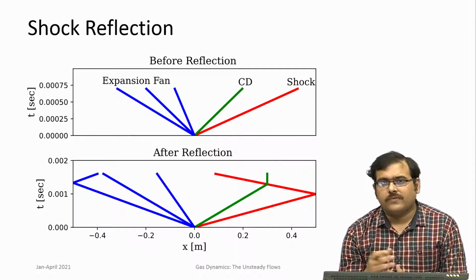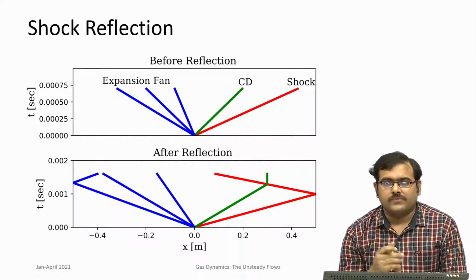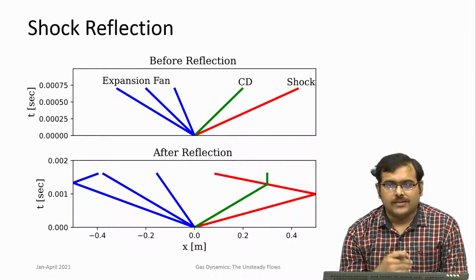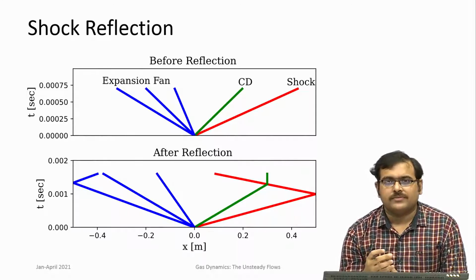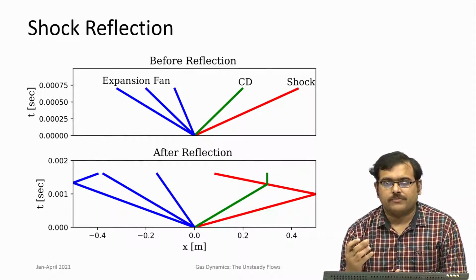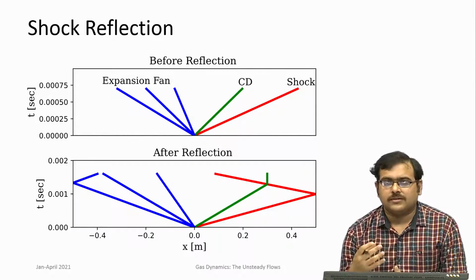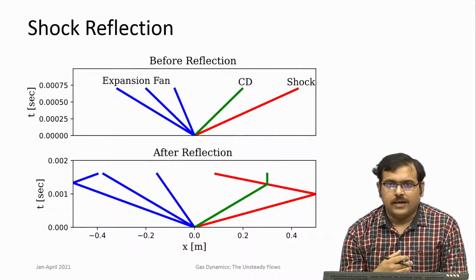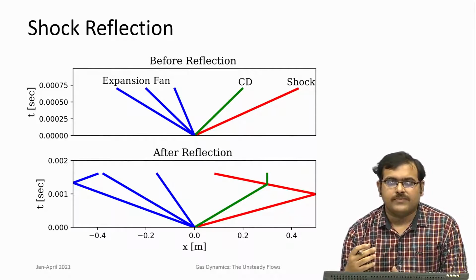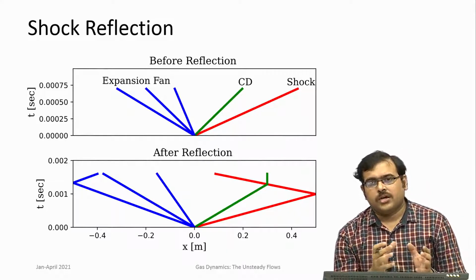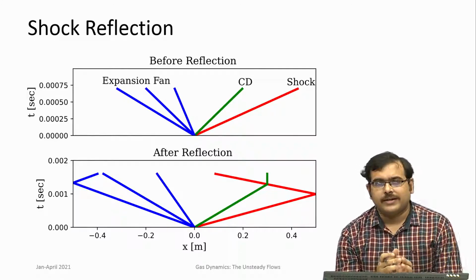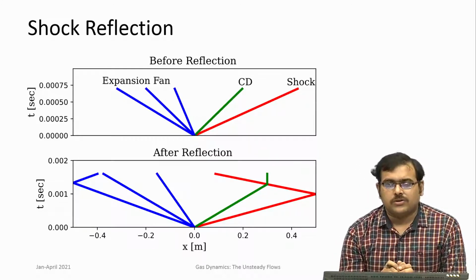because it is all wave dominated flows, you see expansion waves, and there are so many waves here. So, we start with the simple waves, linear waves of pressure, very small perturbations of pressure and density, which are nothing but sound waves, and then we look at much larger strength waves, finite waves, and then we will see how these equations of finite waves model the expansion waves in the shock tube.